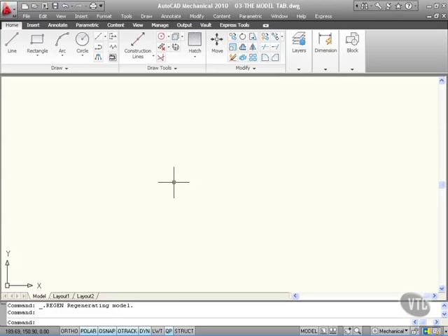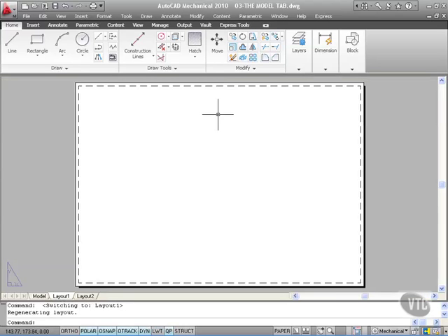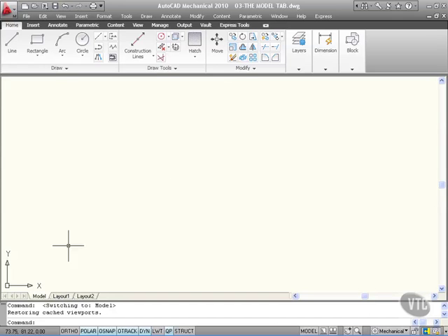For those of you not familiar with AutoCAD at all, work that you do with AutoCAD and AutoCAD Mechanical should normally be done in the Model tab here. And then when you go to your Layout tabs, what you do there is set up your sheet, your title block, your viewports and so on, so that you can view scaled views of what's actually in the model space, the Model tab here.